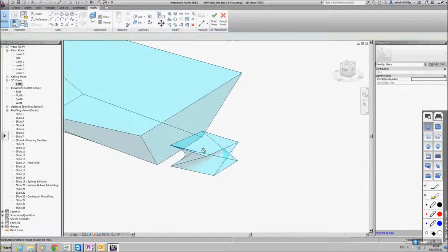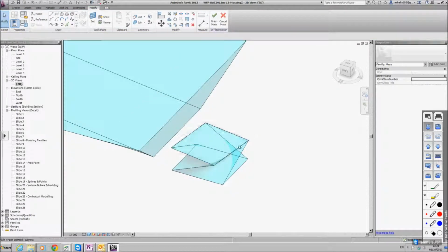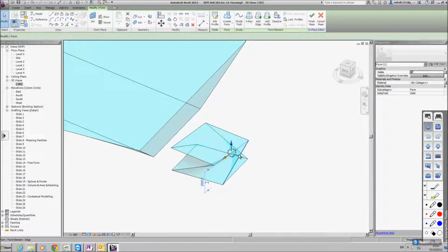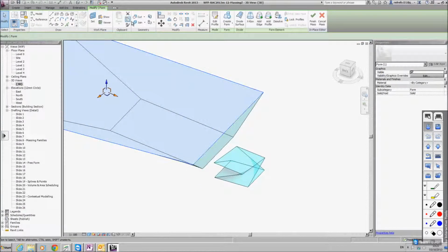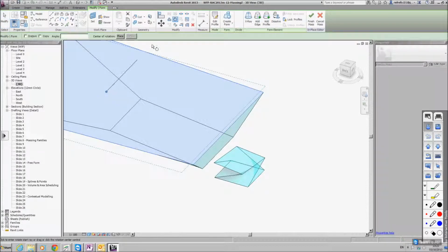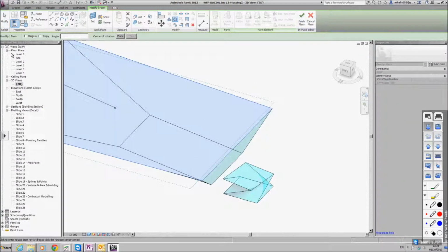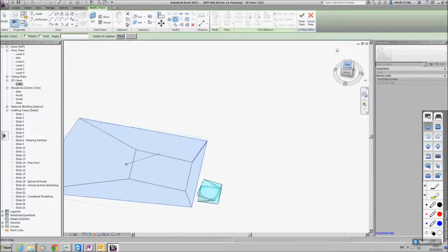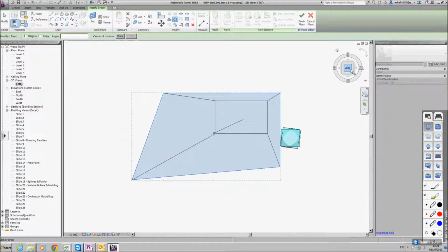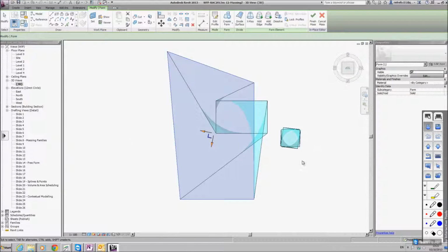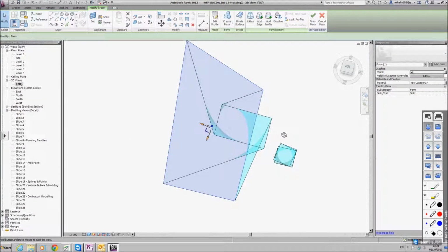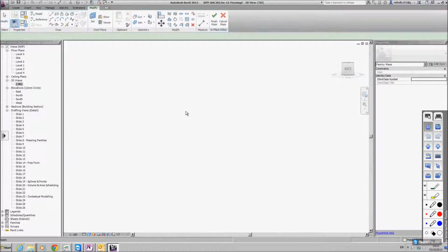So just to show you an example there, you can rotate objects as well as move them. I'll show it with this one as well. You can just click on it and do this from the top. I'll click on my top in my view cube, and I'll rotate this 90. Hopefully, I can do it. Just showing you that.